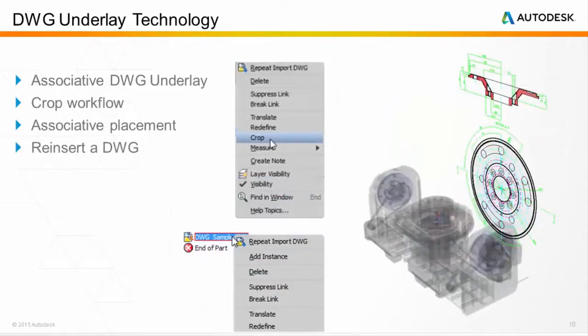You can now include DWG underlays in drawings and do the following. Add text and dimensions to annotate the DWG underlay geometry. You can easily manage the layer styles and line types. You can crop the DWG underlay to improve performance and remove unwanted data in part files. Cropping allows you to focus on the relevant areas of the design when you're working in a large DWG file. In addition, cropped underlay geometry in a part file displays this cropped geometry in the drawing view of the part.